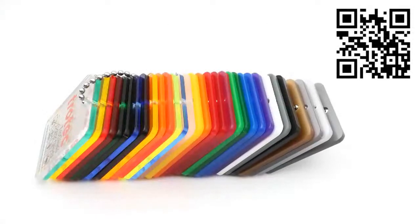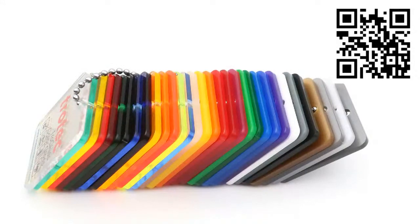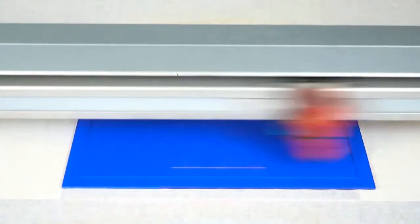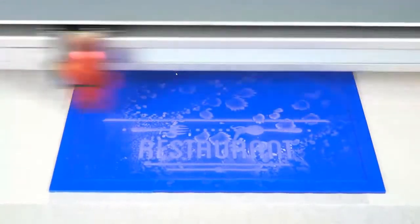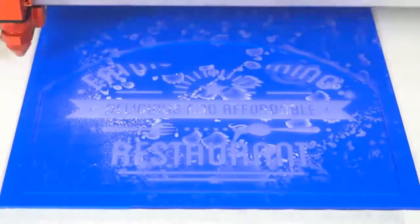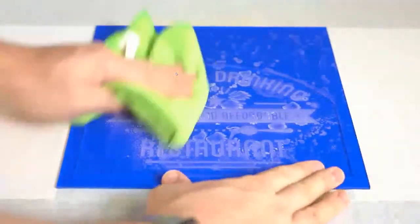I'm going to do this on our frosted acrylic, or our matte, satin acrylic is actually what it is. And here's a QR code. So this is a satin blue acrylic. So it's got a transparent opaqueness to it. And the laser is going to engrave into the surface of the cast acrylic, and then we're going to basically expose that frosted effect into it. And the nice thing about this, because it is opaque, it can be backlit, it can be side lit, it produces a lot of good contrast.